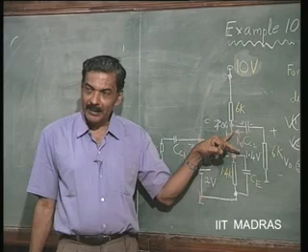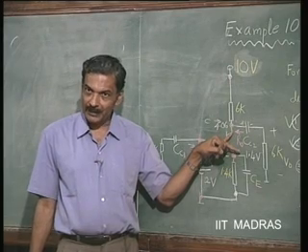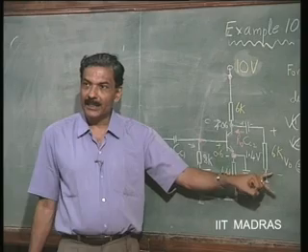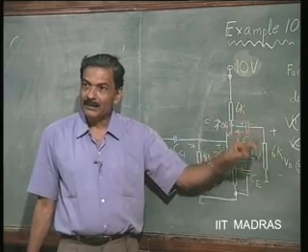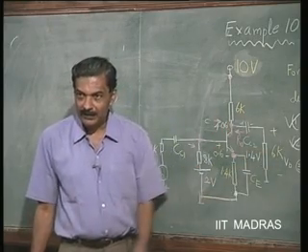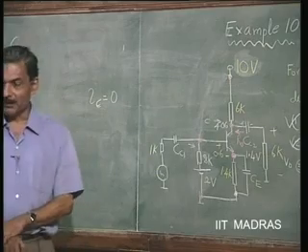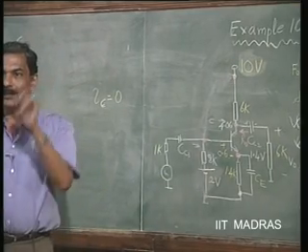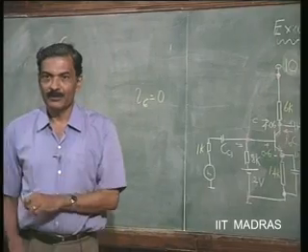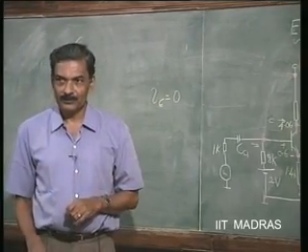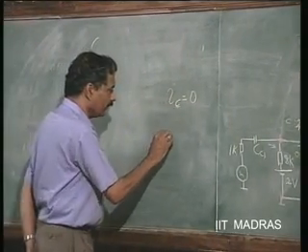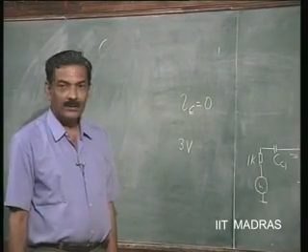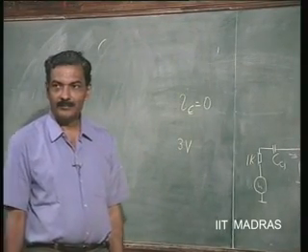If it is 1 milliampere peak swing, that is flowing into a resistance combination of 6K parallel 6K, which is 3K. So, the voltage swing possible before it goes to cutoff is 1 milliampere into 3K, which is 3 volts. So, before it goes to cutoff, it can go to a swing of 3 volts. Is this clear?